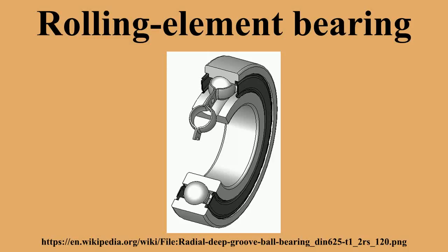The fifth and sixth digits define structural modifications to the bearing. For example, on radial thrust bearings the digits define the contact angle, or the presence of seals on any bearing type. The seventh digit defines the width series, or thickness, of the bearing. The width series, defined from lightest to heaviest, is 7, 8, 9, 0, 1, 2, 3, 4. The third digit and the seventh digit define the dimensional series of the bearing.